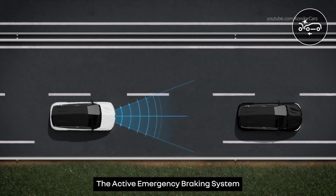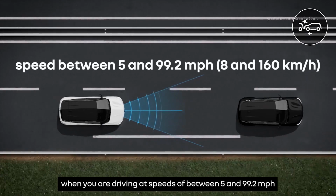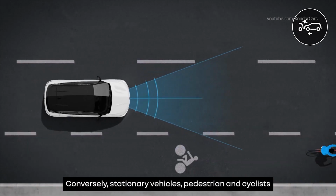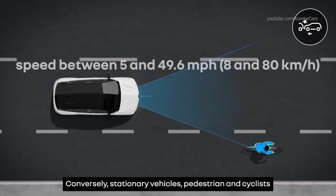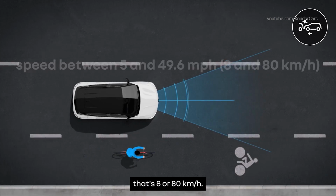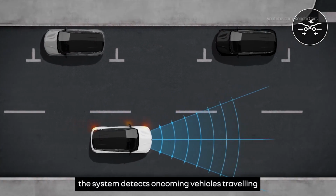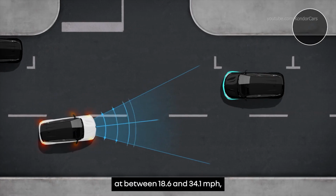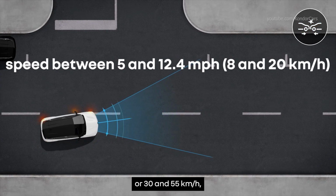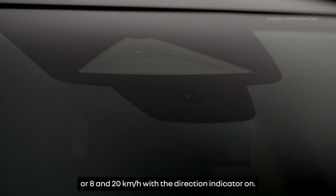The active emergency braking system detects moving vehicles ahead of you when you're driving at speeds of between 5 and 99.2 miles per hour or 8 and 160 kilometers per hour. Conversely, stationary vehicles, pedestrians and cyclists are detected when you're driving at between 5 and 49.6 miles per hour, that's 8 and 80 kilometers per hour. Lastly, when you're at a crossroads, the system detects oncoming vehicles traveling at between 18.6 and 34.1 miles per hour or 30 and 55 kilometers per hour, when you're driving at between 5 and 12.4 miles per hour or 8 and 20 kilometers per hour with a direction indicator on.